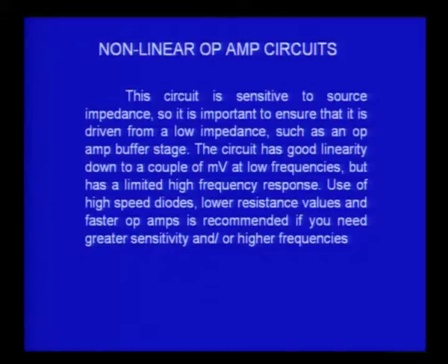All these things we will also see, and you can have a precision rectifier having very good linearity even in the millivolts range. Okay, even a couple of millivolts at very low frequencies, you would find the full wave rectifier works very well without any great difficulty.